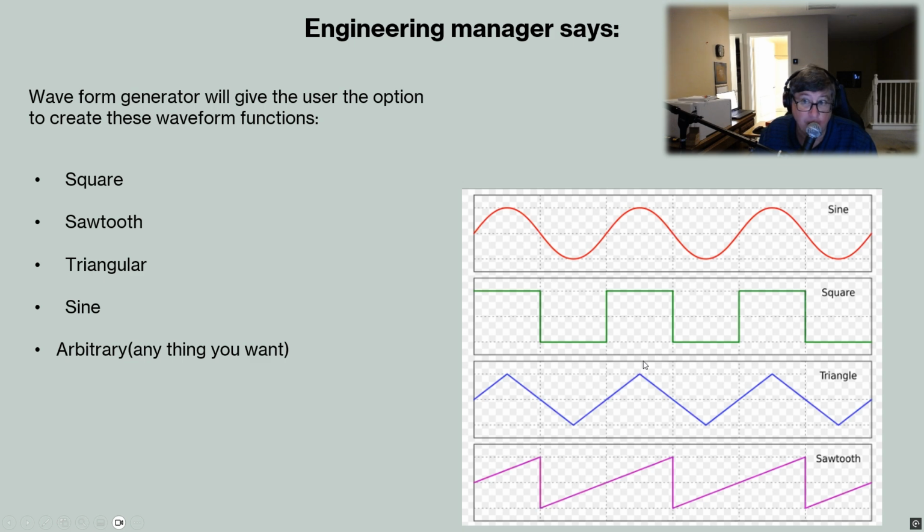these waveform functions. Okay, so we have the square wave. It should appear like that, something like that on the oscilloscope. We got the sine wave. Sine wave is from 0 to 3.3 volts. There's no negative, so consider that. There is a triangular wave that goes from 0, and there's a sawtooth wave, and there's an arbitrary wave with anything you want. Anything you try to be as flexible as you can, but put some creativity in there.